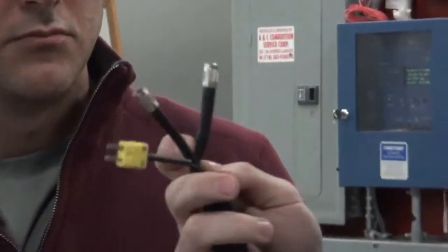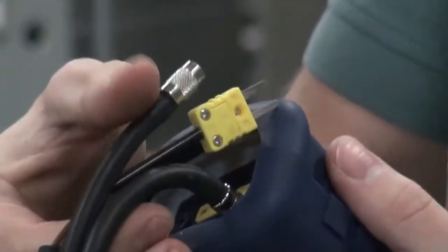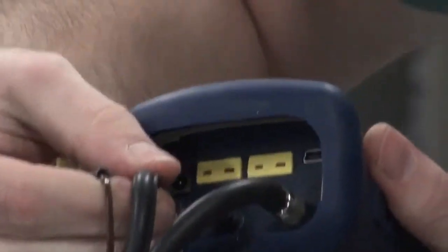We have a larger diameter and a smaller diameter tube. The larger diameter tubing is actually for the vacuum side of the system, and that's going to sample the byproducts. The smaller diameter one is the pressure gauge for our manometer, and with that we'll be able to test our draft.